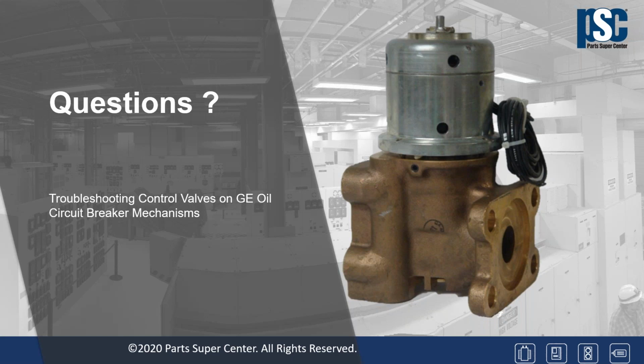So the instruction books talk about lapping the main piston to the valve body using Clover #4 lapping compound. Again, I've had very limited success doing this myself, but I do have some customers that have told me they've gotten good at it, and have actually created a tool to sit into the top recess of the piston.